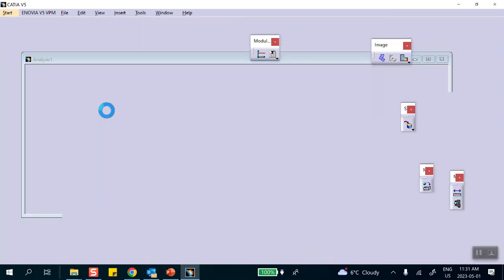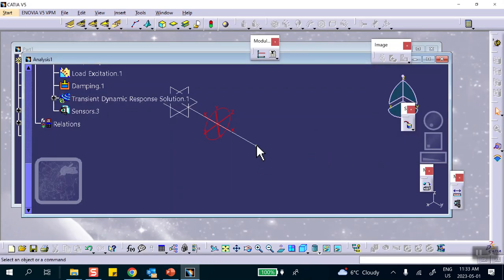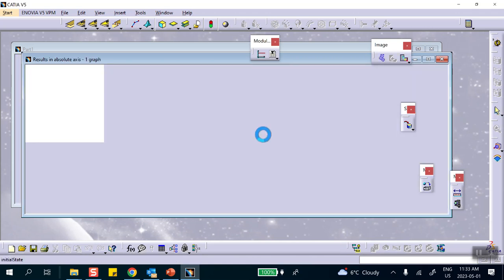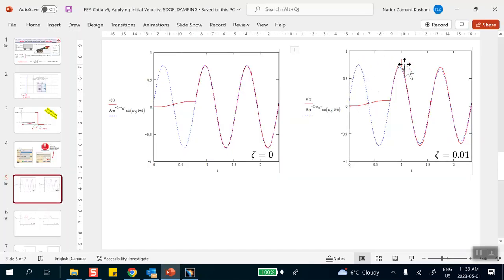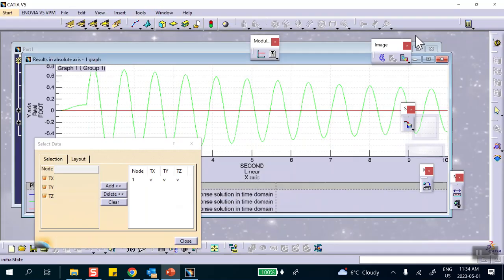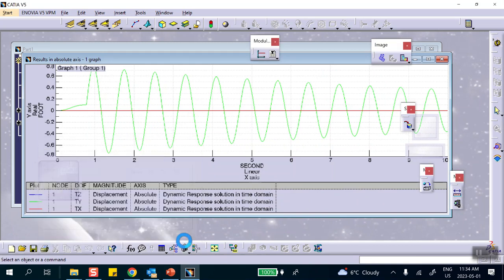Close that. Another one. And check the, yeah. You can see that when you change the number of steps, this height changes. The maximum peak height changes. So right now it's around 0.7, which is compliant with what roughly I have here. So you got to be careful. That's what this was about. If you do not use a sufficient number of steps, the results depend heavily on that number of steps.